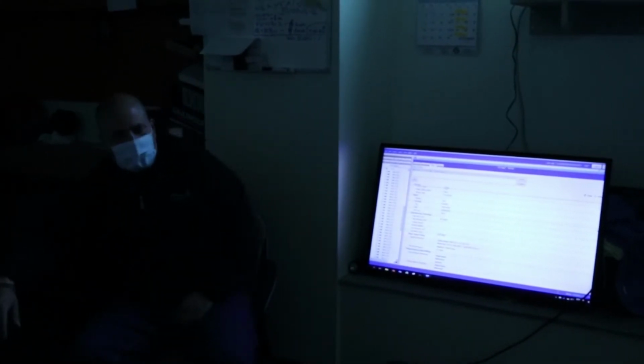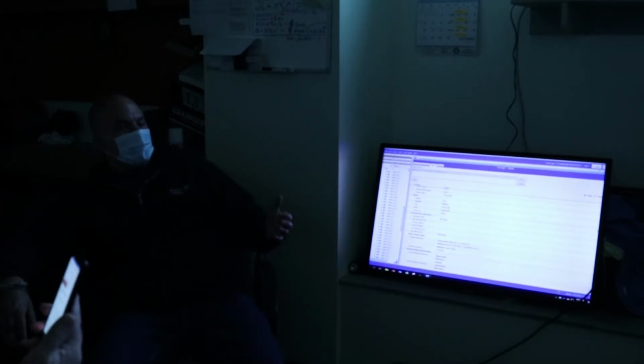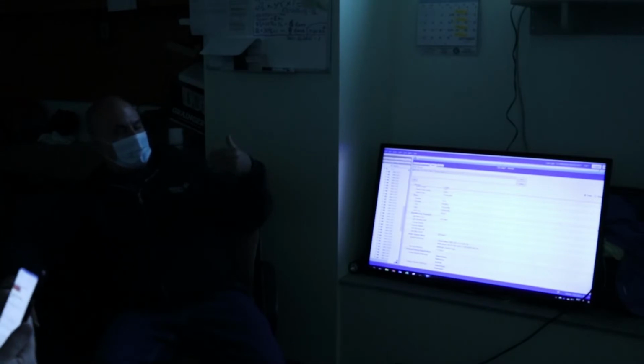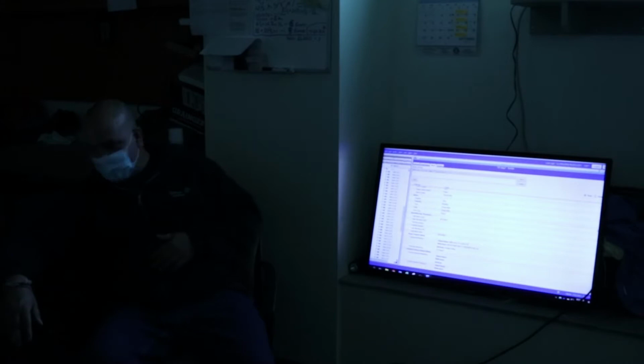On certain alarms, you could also reference a set point, so the limit is a number of degrees away from the set point, not just a fixed high limit. If it's something where you adjust the set point a lot, that may be how you want to do it.